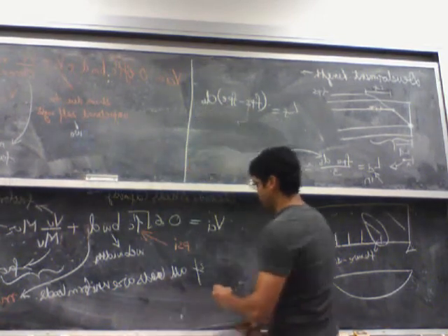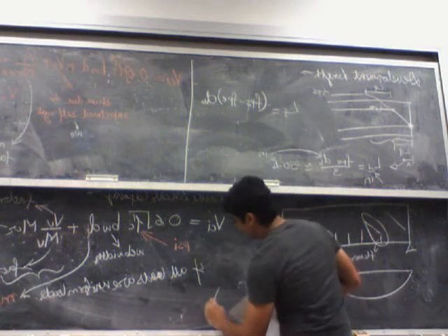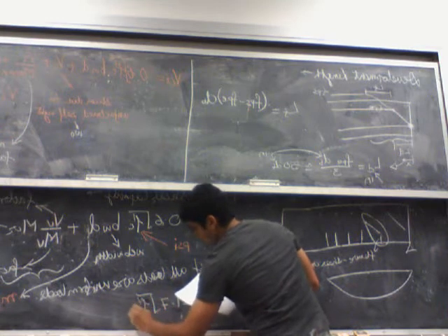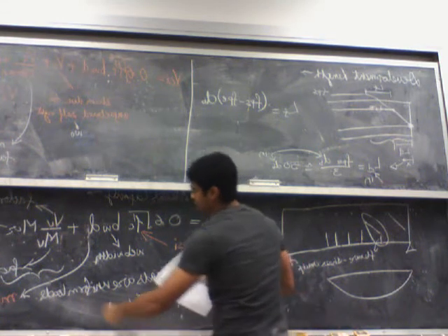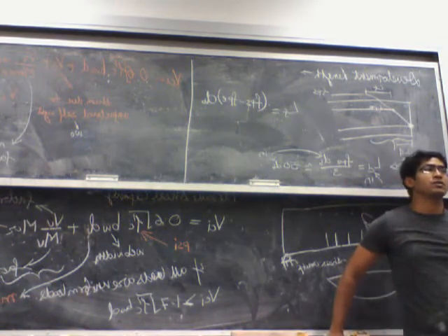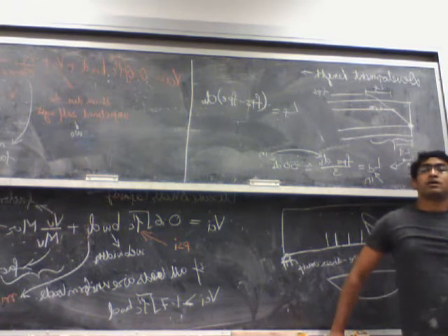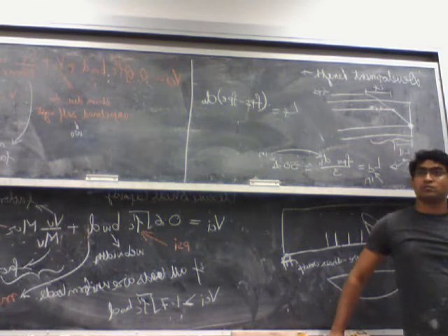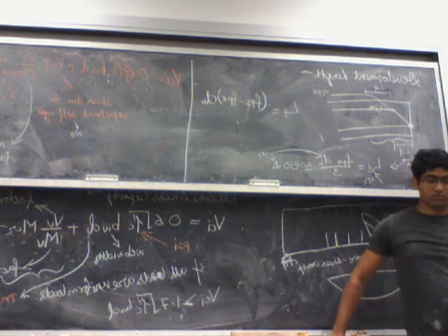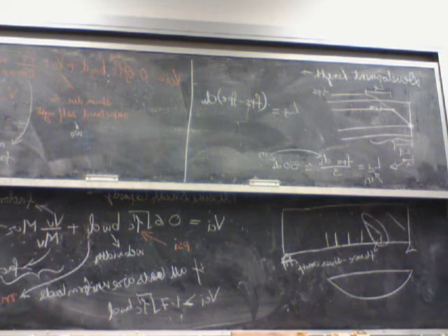And there is another limit which says that Vci from both of these formulas has to be greater than or equal to 1.7 square root f'c bw d. Again, this d is the same as right here, the maximum of dp or 0.8 times h. I was wondering about d: there are times where you write the equation and specifically say that d is to all the pre-stressing steel, including mild reinforcement, and sometimes you'd say dp is only to the pre-stressing steel.